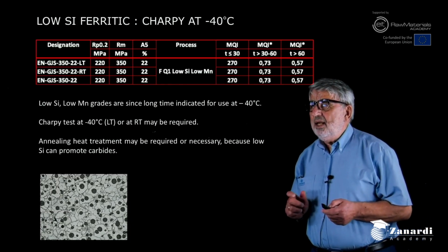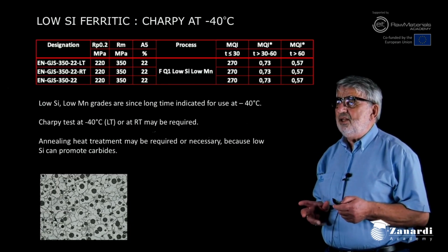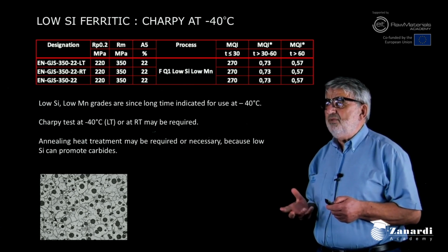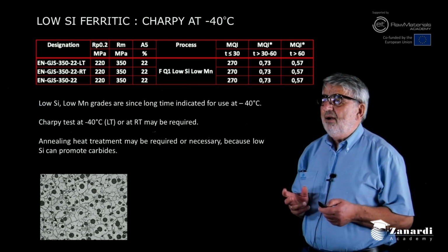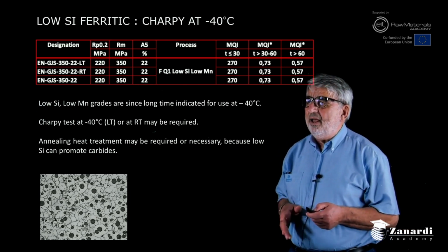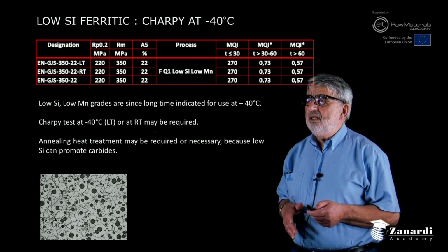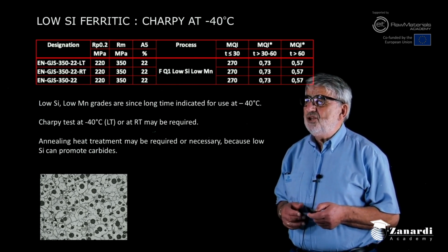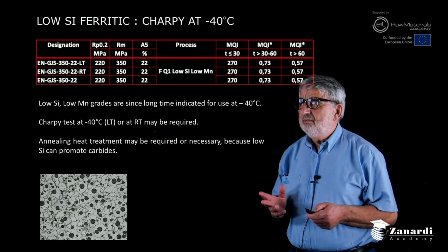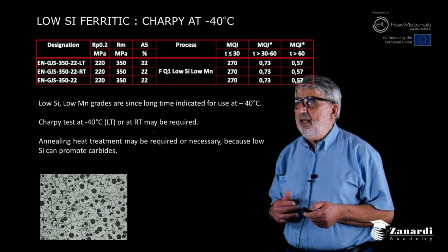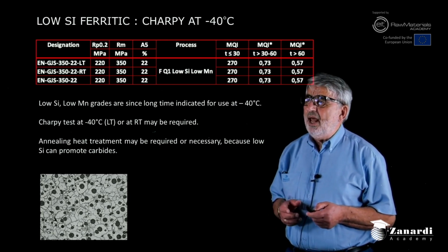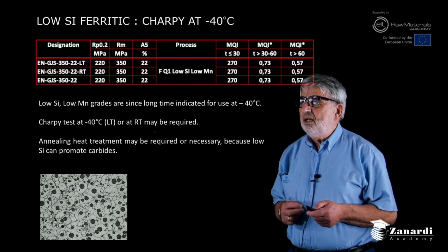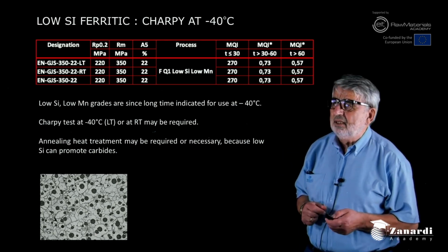So in the international standard you find the specifications for grades that require a given Charpy minimum impact energy at -40. These are typically quality grades with a low silicon and low manganese content.